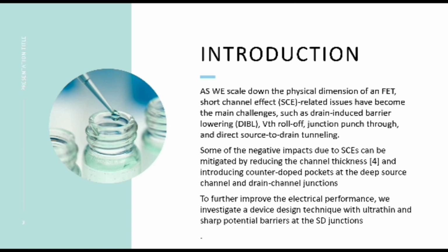And in this paper, a device design technique using tunneling barriers for reducing the short channel effect is proposed by introducing a tunnel barrier at the source and drain junction of the silicon FET. The threshold voltage roll-off can be significantly suppressed. This is because the tunnel barrier weakens the electrical coupling between the drain bias and the transmission spectrum in energy.